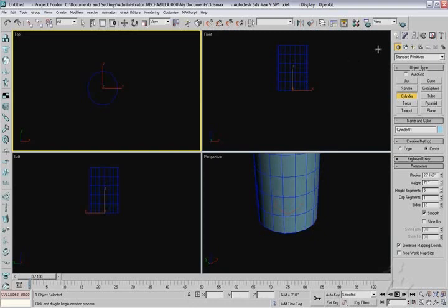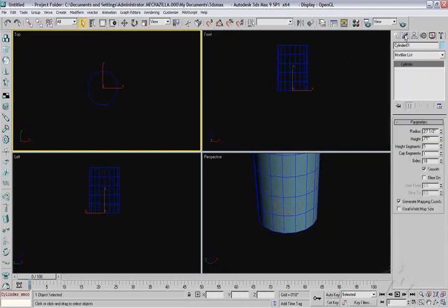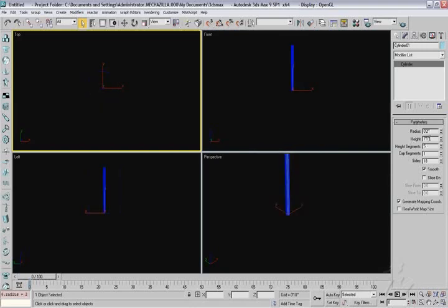And we'll go over to the modifier panel now and change some of the parameters of our cylinder. For starters, I'm going to change the radius of this down from 2 foot 7.5 to, say, 0 foot, probably about 2 inches in diameter, make it much skinnier.